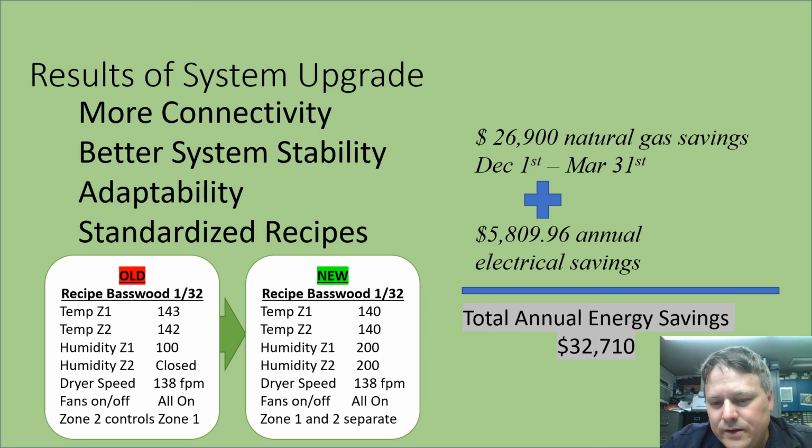We measured the airflow leaving the dryer, and we were able to capture the amount of heat we were exhausting to atmosphere, and we can correlate that back to natural gas usage. We were also able to reduce the amount of fans we needed to run to dry the same amount of veneer, which saved us significant amounts of money in electricity.